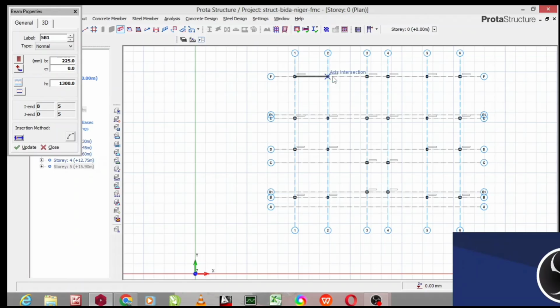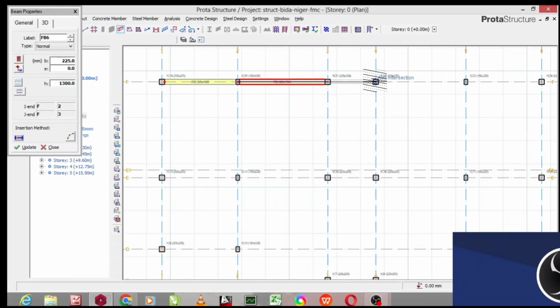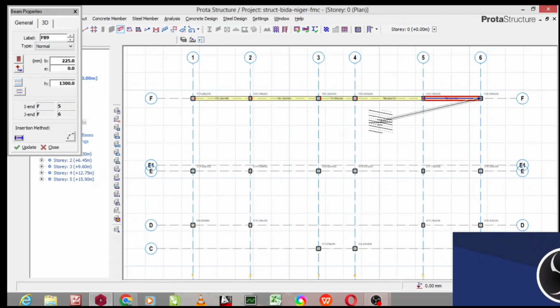Also, one very important thing that needs to be done before you choose the kind of foundation you would like to use is a soil test. A geotechnical engineer needs to take soil samples to the lab.